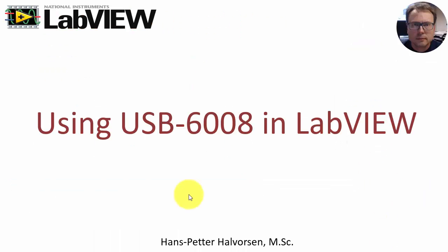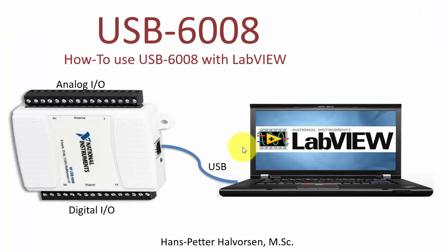So now we will connect the USB-6008 DAQ device to the computer and see how we can use it within LabVIEW. So here is how you connect it. You just connect the USB cable between the USB-6008 device and the computer, like this.